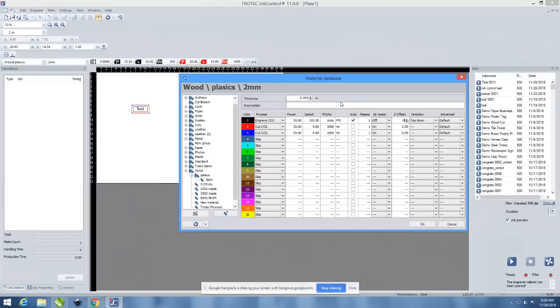Perfect. Thanks, John. And also, Anthony, I should mention the Z offset, we have multiple videos. Like the out of focus method, I think that Mike Clark did. If you want a blacker engraving on the Trotec plastics, you might want to put it a little bit out of focus. Again, I mentioned with the acrylic, if you're in focus on the acrylic, it'll engrave white.